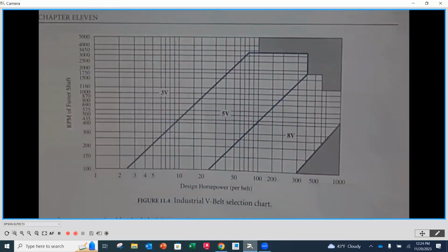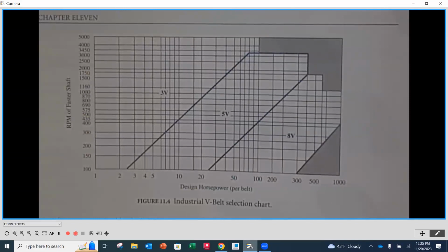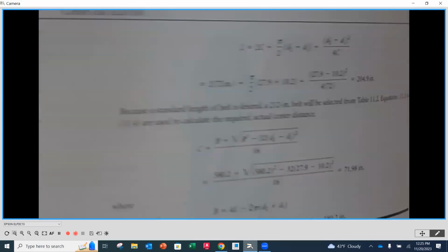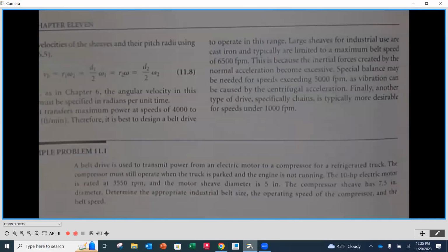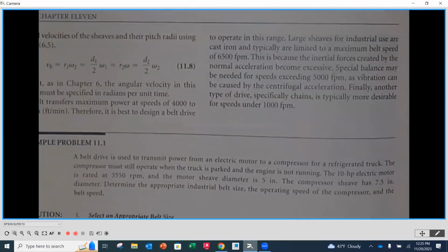Okay, so in the instance of gears, we call that pinions. In here we either call it a driver or a driven sheave or pulley, for a V-belt. So a driver is going to be the faster of the two. The driven is going to be the slower of the two. So if it's a direct application, for instance, where we're coming right off of a motor and attaching to, I think a little bit later, we're looking at some sort of an industrial mixer, or this one's a grinding wheel.